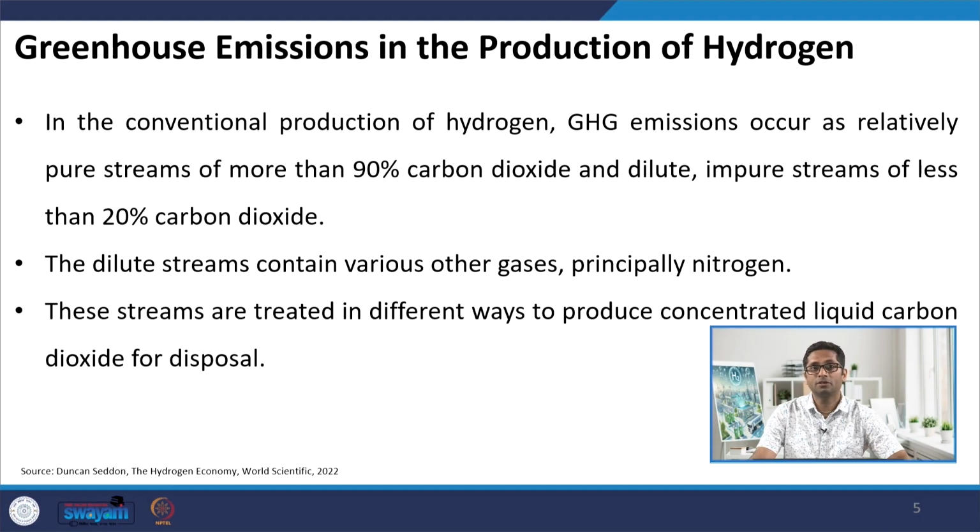Then another major stream happens after the water gas shift reaction. After the water gas shift reaction, I would have some kind of carbon capture technique to come in, wherein I am capturing all the CO2, and that leaves me with almost pure stream of hydrogen. This stream is much more concentrated stream, easier to capture and easier to get sequestrated as well.